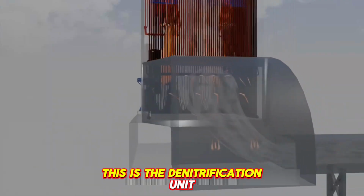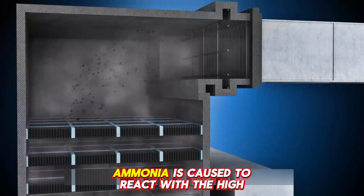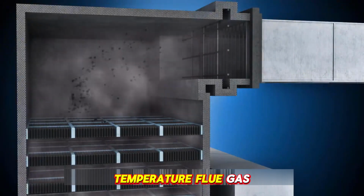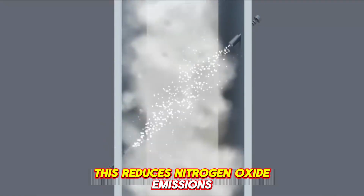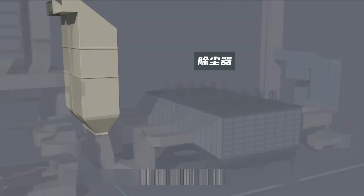This is the denitrification unit. By spraying a denitrification agent into the reactor, ammonia is caused to react with the high-temperature flue gas. This reduces nitrogen oxide emissions. The treated gas is then sent to an electrostatic precipitator.